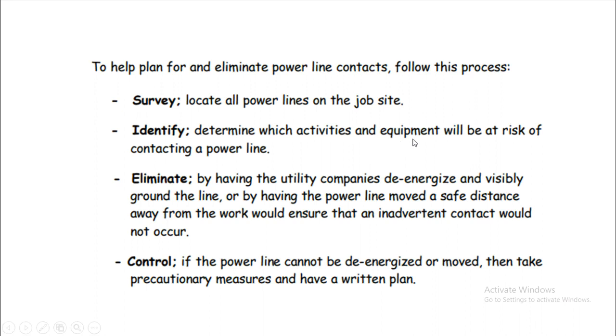And also for the equipment, we can check, for example, the height of the equipment that needs to pass under the overhead power lines. So you can identify the height of the equipment and whether this complies with the minimum clearance above from the topmost parts of the equipment. Otherwise, change the equipment or don't pass that way.